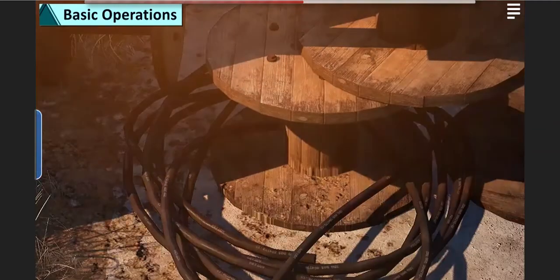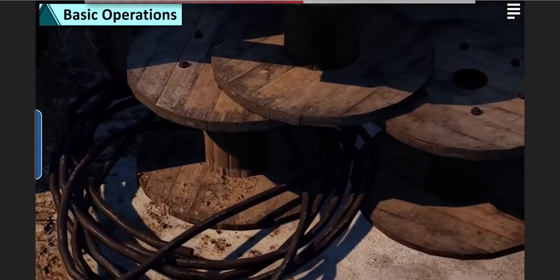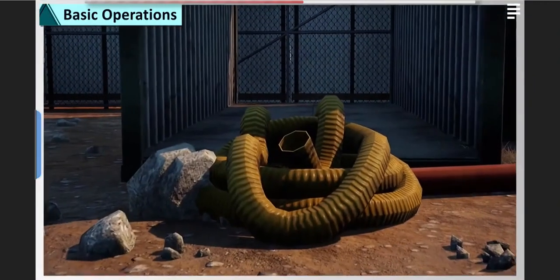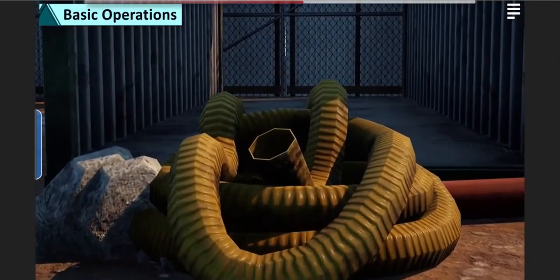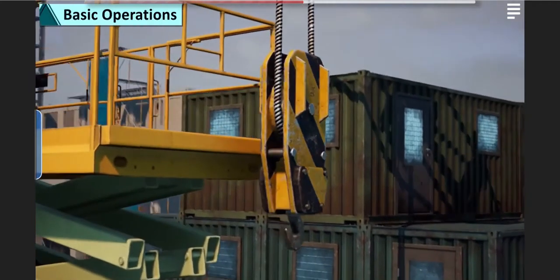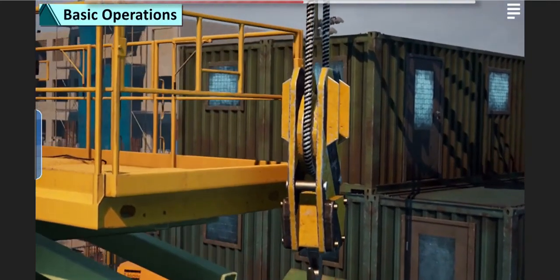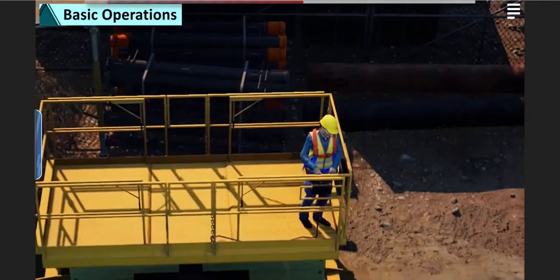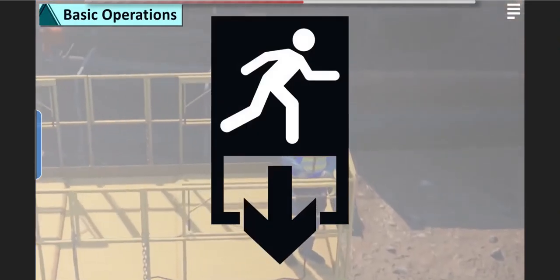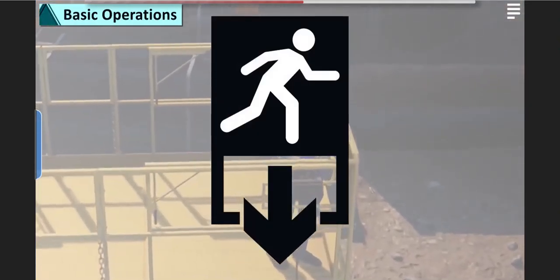the work platform. Be careful not to let equipment such as ropes, electric cables, and hoses become entangled in the MEWP or adjacent structure or objects. If the work platform, extension, or elevating assembly becomes caught, snagged, or otherwise stuck, all operators and occupants must be safely evacuated from the work platform before attempts are made to free the MEWP.